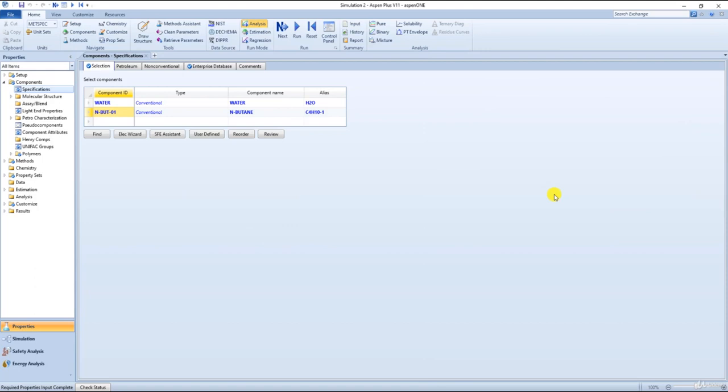Now, before moving on to the next video, keep in mind that the property method selection will be revisited in each successive section, as it is the heart of any simulation process. Hopefully, toward the end of this course, you will master the process of property method selection based on the given chemical process being handled. What I want you to keep in mind at this level is that the idea behind presenting the choice of having more than one property method for a given process system is simply that one method may be superior to others in terms of getting a converging solution and realistic results.